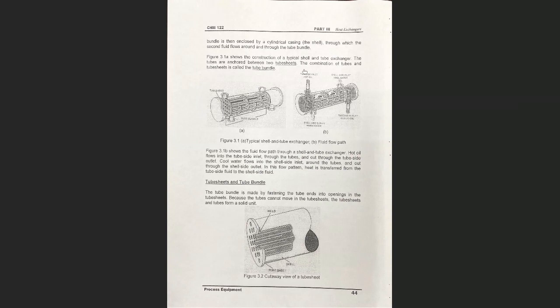We are doing a cooling process. In this exchanger, the mechanical design allows the hot oil to flow through the tubes only. The oil enters only the tubes, flows through the tubes until it gets to the other end, through the discharge flange, and continues to flow in the downstream piping system.